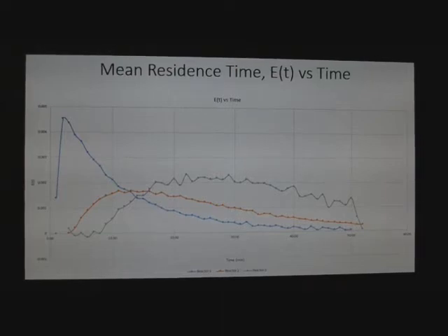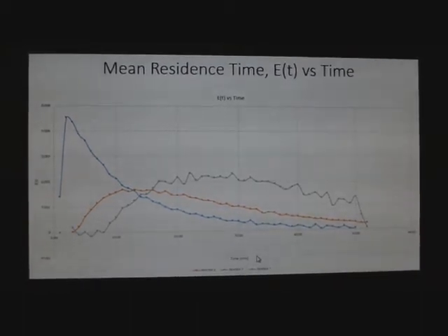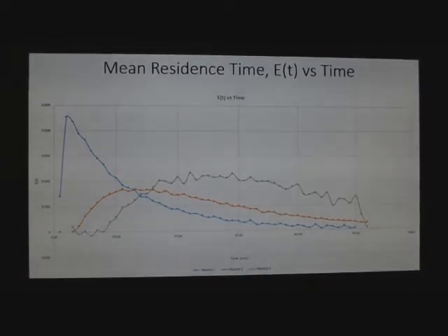Next, for the second graph, mean residence time of reactor 1, the blue color, it increased sharply, but after a few minutes it dropped drastically to 0 at 40 minutes. This is because the solution is being passed on to reactor 2 continuously.